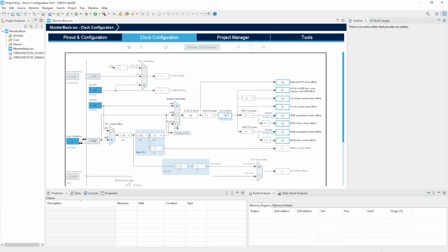I'm gonna set the maximum possible speed for the H clock line. So I'm gonna use 168 MHz. I'm gonna press enter, and as you can see here, it's gonna provide the necessary configurations for that. So look at that, very important.